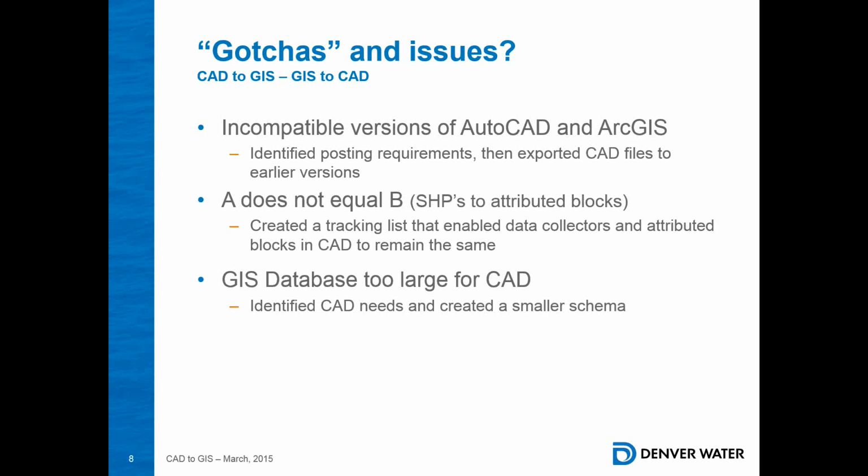Quick tip from me to you: one of the biggest gotchas that took us the longest time in the world to figure out was this. When Esri's database locks up, Esri's software will keep spinning and keep pinging it and wait until it comes back, and then pull the information back up. But if you're in Autodesk applications and you're tied to the Esri database when it locks up, AutoCAD will crash. Hard.